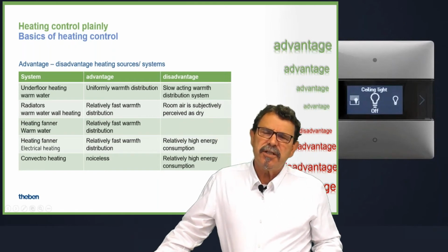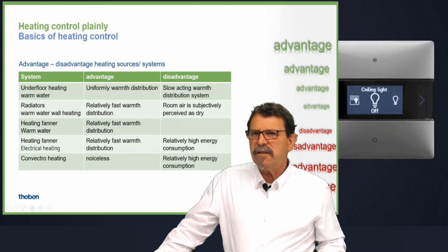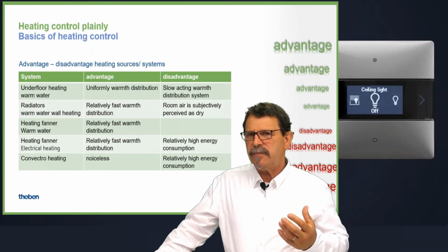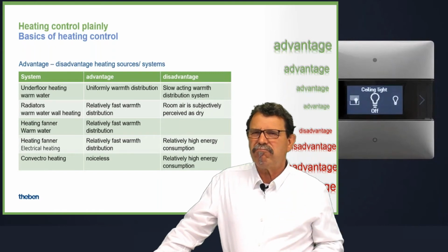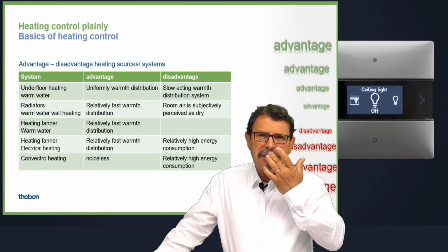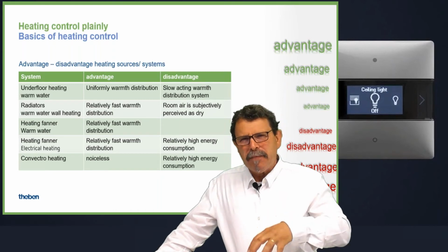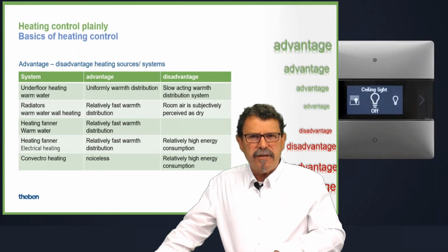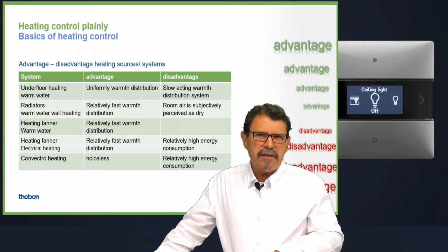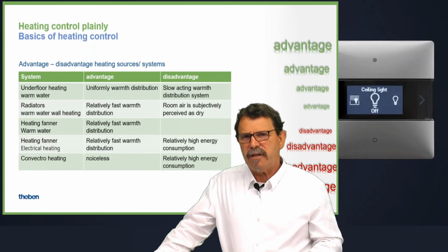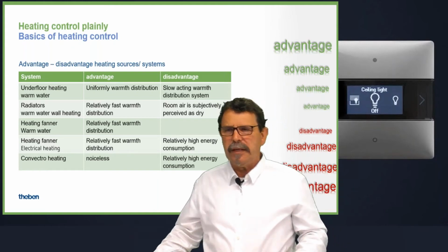The disadvantage in this case is that the air is rather dry, especially during the heating season. That's related to this heating procedure. When we have underfloor heating, for instance, it's not that tremendous. But when it comes to radiators, you have mostly dry air, so you have to humidify, mostly in the heating season. This we have to do.